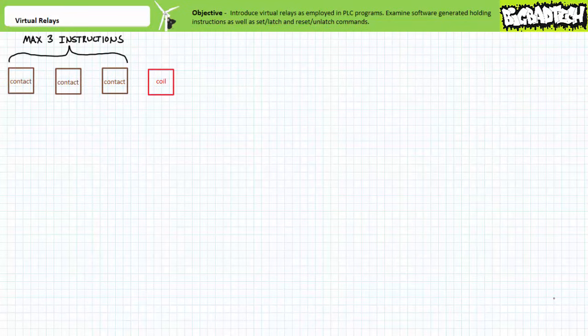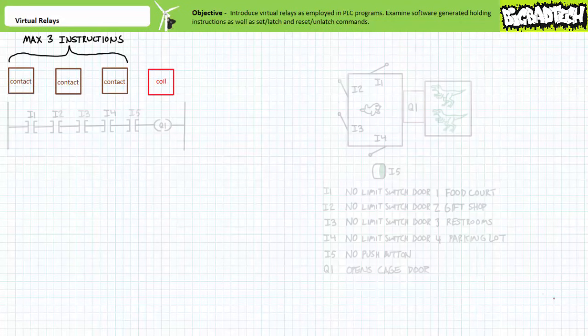Consider, however, an application necessitating a safety chain of 4 or more elements, any one of which would prohibit safe operation of a system. A safety chain is constructed by the logical AND operator, being a series connection of those elements that prevent startup of the system. If any element in the safety chain prohibits logical continuity, the safety chain is broken. All elements in the safety chain must be in agreement for safe operation of the system.